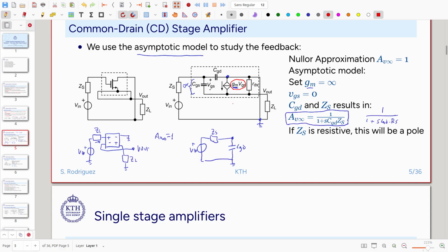We're going to replace this by a constant value. Let's see, like this. We're going to replace this one by a constant current source, okay, with the same direction, and I'm going to call it a test current source, IT. So we are replacing this variable with a constant current source, and then my objective will be to see how much of the current that I have applied here comes to the terminals VGS. And when I calculate this one, this is going to be my feedback, the beta factor.